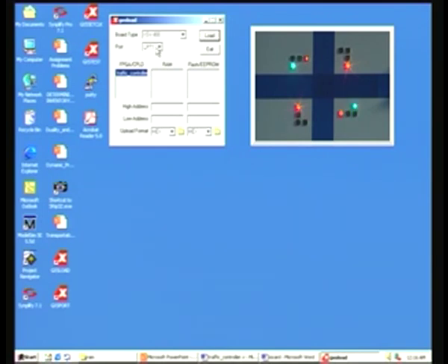The bit stream that you need, for example traffic underscore controller, which is actually a dot bit file, we had to get in this field by merely copying and dragging from the folder in which it is available. This is what we have already seen in the previous designs, and once you have got the file on this, you have to load that.